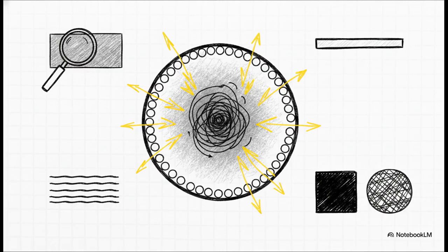This higher inductance acts as a stronger resistance, or reactance, and literally pushes the alternating current outward toward the surface. The result? The effective usable area of the wire is actually reduced, which slightly bumps up the overall electrical friction. And this effect gets worse depending on the material, if you're using a larger diameter wire, a higher frequency, or if the wire is a solid piece rather than a bundle of strands.